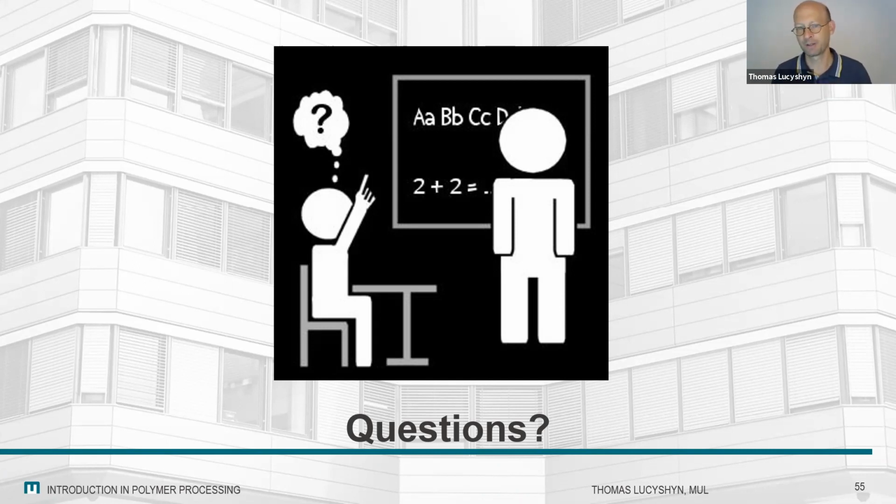But still, the primary process of mixing happens in a compounder, which is a twin screw extruder. So 2 screws which have a very good mixing effect, but are not intended to be used for the production of films or whatever. And the effect of fillers is, of course, that it changes the flow behavior. So if you add liquid fillers, it might reduce the viscosity. If you add particles, it might increase the viscosity. That all has an influence on the flow behavior.